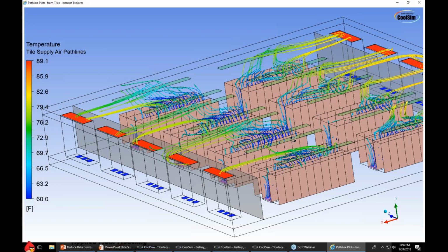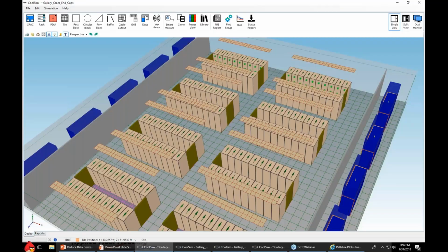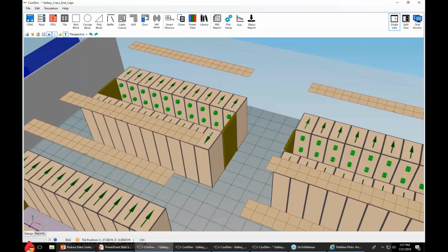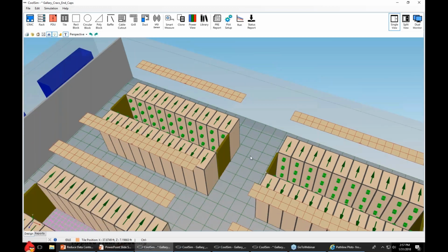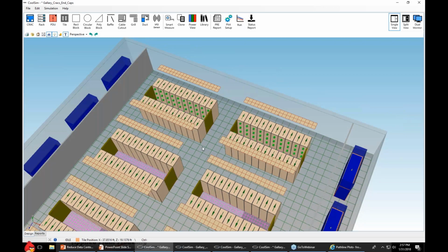If it's a temperature sensor, you should do what I did in this model, and that is put them in a variety of locations. In a design like this one, and I've only got them up here on this one, you want to be careful about the top of those racks, because that's where you're going to get recirculation. You're going to get overage, these corners in particular. So you want three, low, medium, and high, across each rack. Now, a lot of people stumble on that because it's expensive. Those sensors are expensive, so they only want to put a couple in. Well, where do you put them?